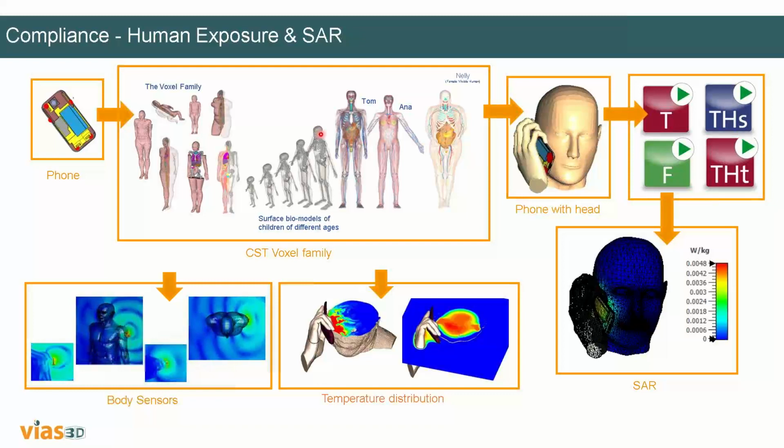Now, most important, you do everything, but human safety is more important. You have to comply with the international standards for the base station, like ARPANSA or ICNIRP standards. If you're considering a handheld device, the SAR is one of the essentials. Again, this is not completely true for applications including millimeter wave. There, power flow is more important than the SAR analysis, because the penetration of the radiation into the body at millimeter wave is phenomenally less compared to the sub-6 GHz frequency bands.